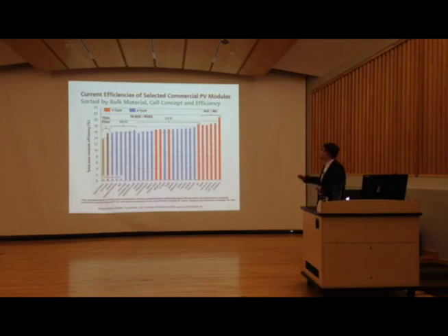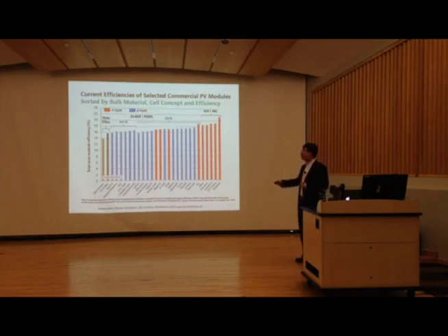And if this is a polycrystalline silicon, that's this plot, the efficiency is still about 16%. If it's a thin film, if it's First Solar, cadmium telluride, it's close to 16%. If it's the other company called Solar Frontier, it manufactures CIGS solar cells, close to 14%.